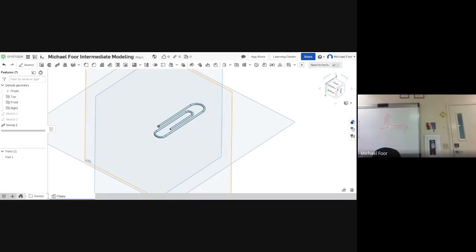Oh, you know what? Your lines might not be touching. Your sketch may turn those lines, because if they're separated even by a small gap, it means that it probably isn't connected. I want to double check the sketch, maybe redraw that, because it looks like it didn't actually connect.